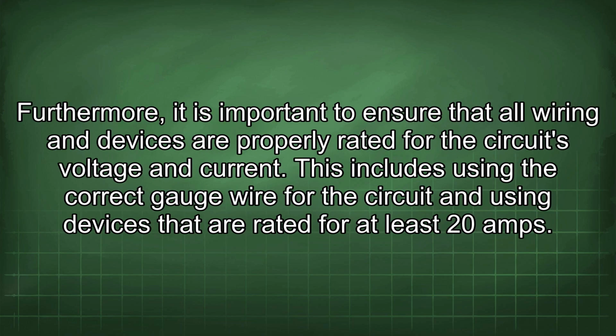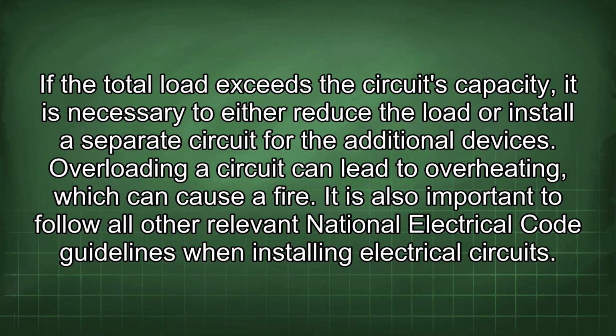Furthermore, it is important to ensure that all wiring and devices are properly rated for the circuit's voltage and current. This includes using the correct gauge wire for the circuit and using devices that are rated for at least 20 amps. If the total load exceeds the circuit's capacity, it is necessary to either reduce the load or install a separate circuit for the additional devices. Overloading a circuit can lead to overheating, which can cause a fire.